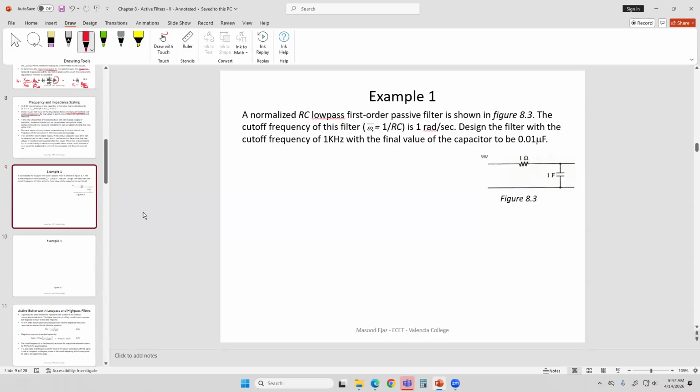So in this case, the output exists at low frequencies because the capacitor starts from an open circuit and then goes down. You still have some output until the reactance becomes very small, so that most of the voltage is dropped across the resistor and very little across the capacitor, because they're connected in series. So that's the justification. That's what you write down or explain if somebody asks why it is a low pass filter. It's because of the impedance of the capacitor.